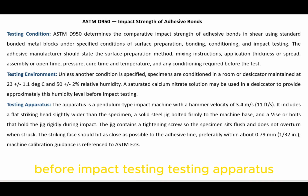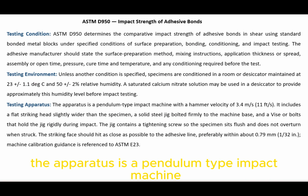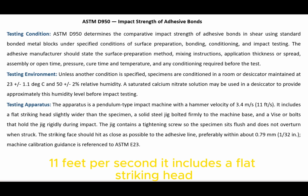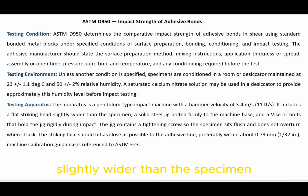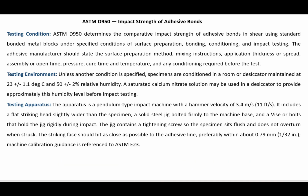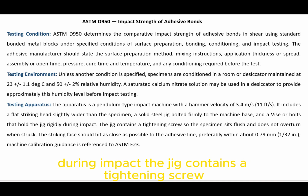Testing apparatus. The apparatus is a pendulum-type impact machine with a hammer velocity of 3.4 meters per second, 11 feet per second. It includes a flat striking head slightly wider than the specimen, a solid steel jig bolted firmly to the machine base, and a vise or bolts that hold the jig rigidly during impact.